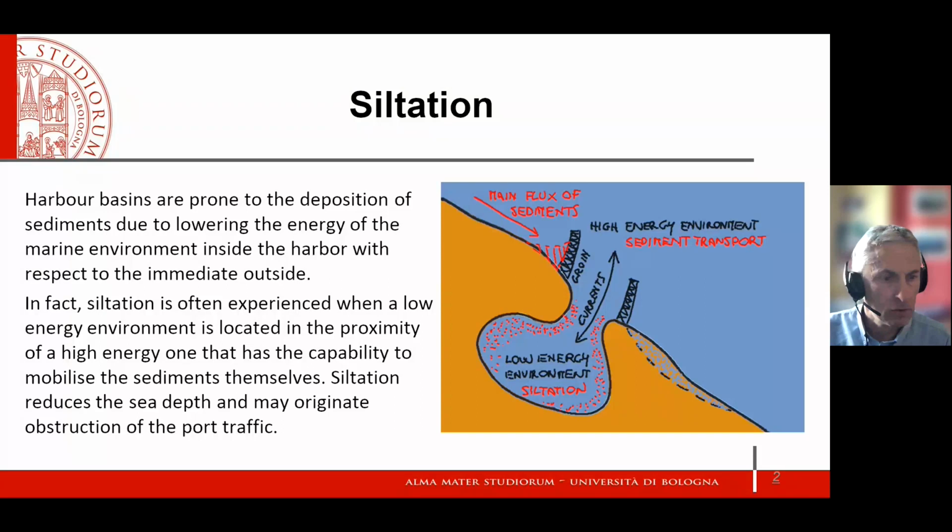You may remember the video of the case study where the realization of groins caused deposition of sediments upstream of the flux of sediments and a corresponding erosion downdrift, like you can see in this picture. In this picture, I highlighted in red, at the left groin, the deposition of sediments, and at the right groin the erosion along the coastline.